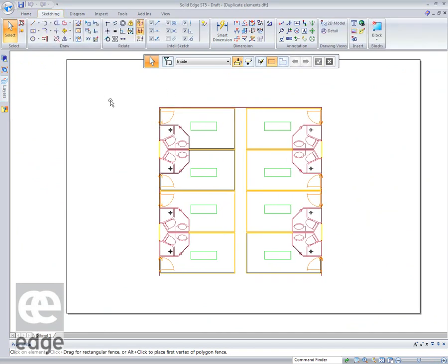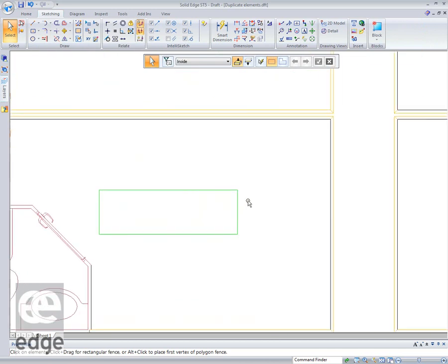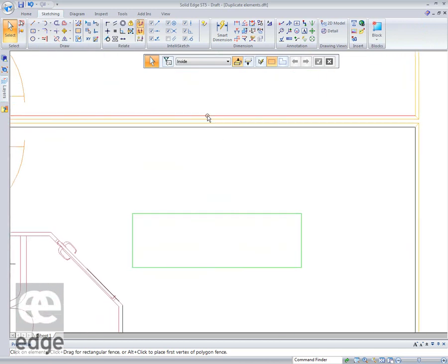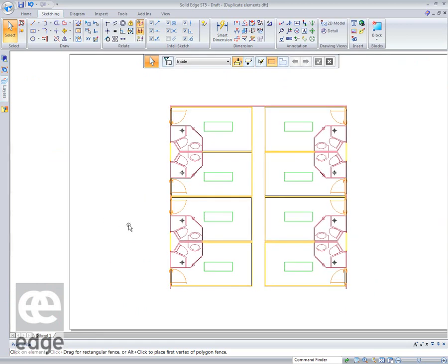Again, we go to our sketch, pick up the Clean Sketch tool, using the same defaults as we had before, click Finish. It's that fast. Now when we go to those lines, hover over a line, no dots from Quick Pick, so I've cleaned that one up. This is a very powerful tool. I think this will, for people who are dealing with imported sketch geometry or drawing geometry, this will be a godsend. There's no doubt about that.